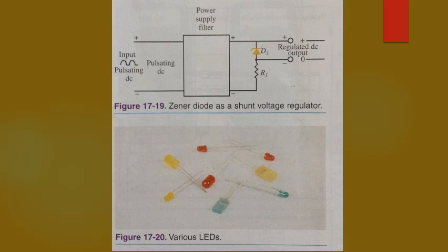An LED receives energy from a DC power supply or a battery. This causes the electrons and holes to combine in the p-n junction region of the diode. This combination creates photons, which are particles of light that can be seen. Each photon is produced from one hole, positive charge, and one electron, negative charge. Different LED colors are achieved by using different materials in the manufacture of the LED.